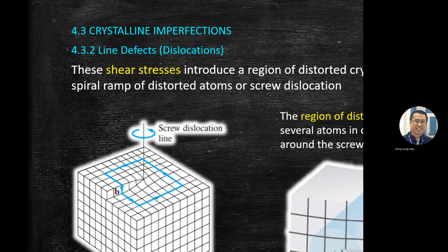stress. So it depends on the direction, or we call it the vector of your force. Okay, so you need to be careful. Sometimes tensile, sometimes shear. Don't assume that all forces at 90 degrees or shear loading are the same. They are not the same. Tensile loading is always 90 degrees. Shear loading is always parallel to the area.